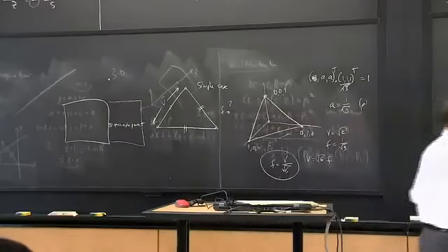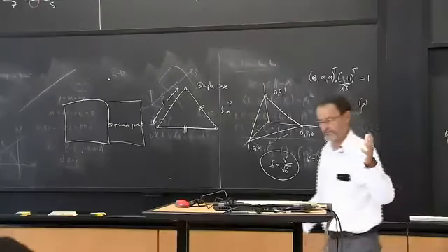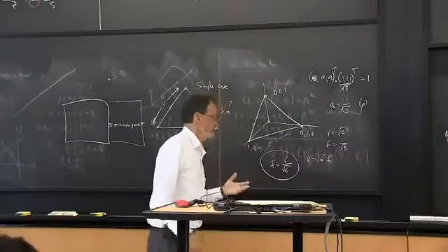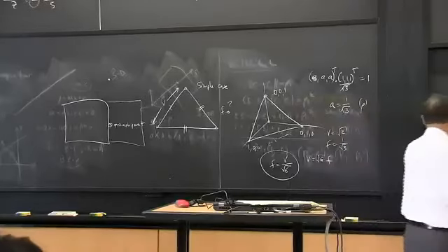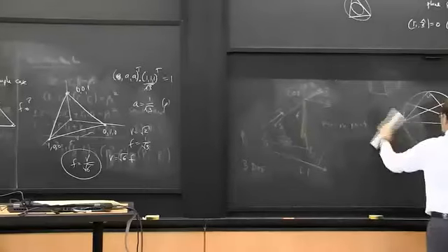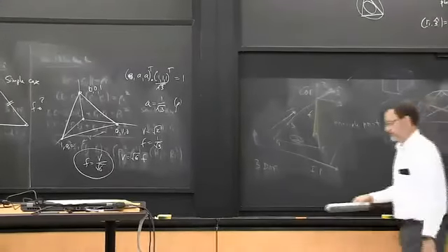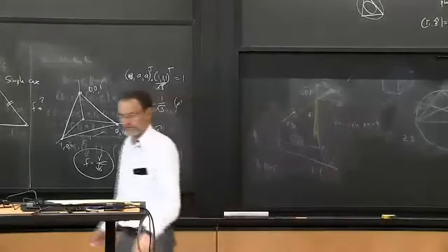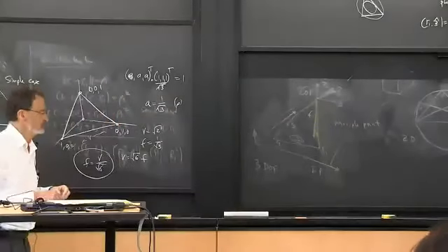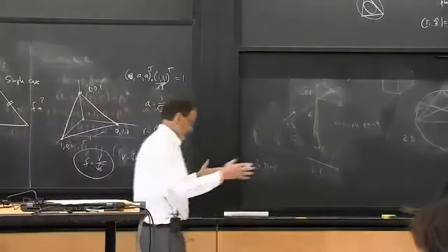Now I want to talk about another application. I mentioned the case where we just slap a cell phone camera onto a car's window, and we want to relate the images we're seeing to some sort of three-dimensional world coordinate system just by identifying features in the image. So what sorts of things can we see in the image? Well, if it's on a straight road, we'll see the curb, and we'll see road markings, and those are supposedly parallel.